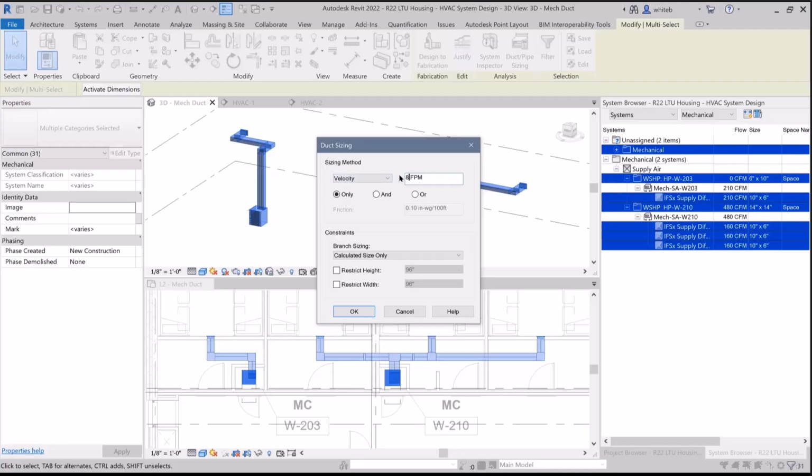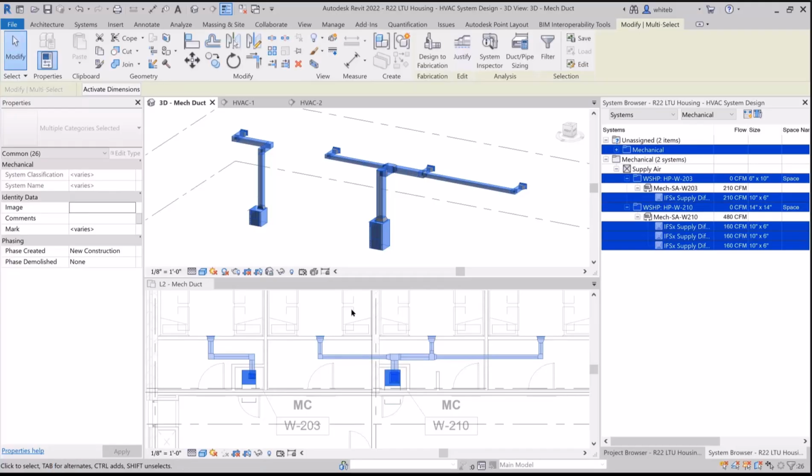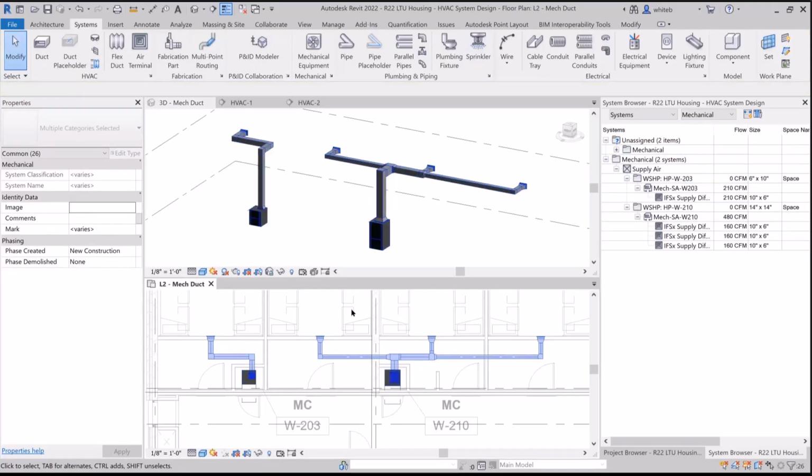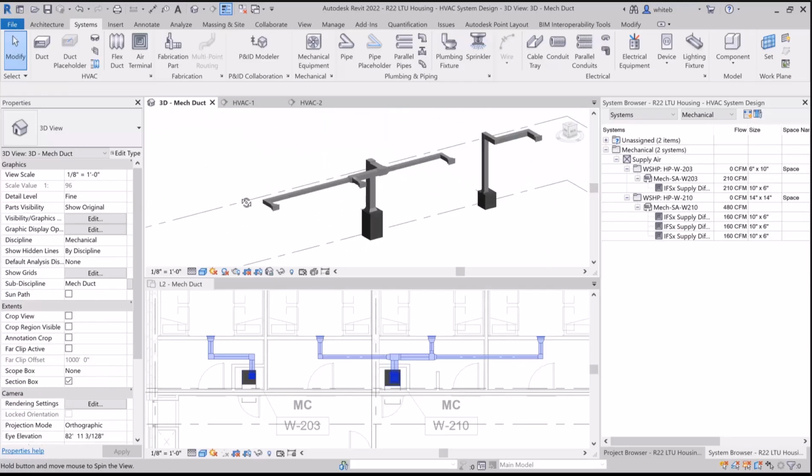Revit calculates pressure losses based on duct geometry, roughness, air density, and viscosity, requiring a connected duct system with valid airflow. Airflow for equipment is calculated as the aggregate of downstream components. Revit will size ducts based on the parameters you've set, making adjustments easy when changes occur.